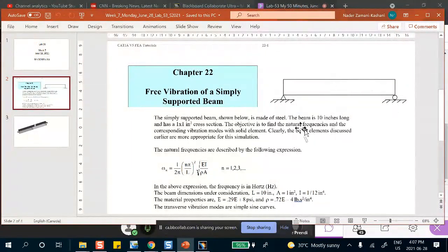It'll go as a full sine wave. The simplest one is the half sine wave, like this, and at that frequency, it will vibrate like this. If you had an initial arrangement so that it was a full sine wave, and then let it go, it's going to vibrate indefinitely in that shape at a different frequency.